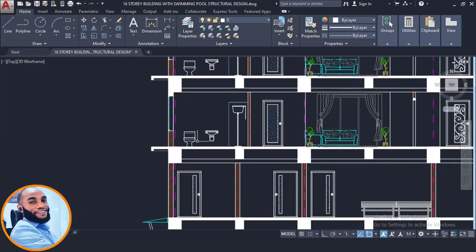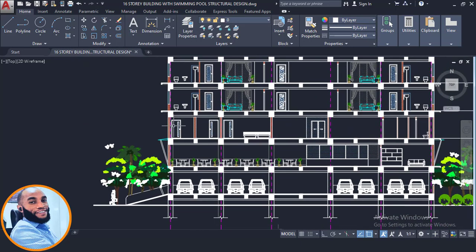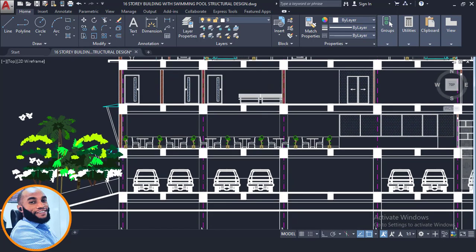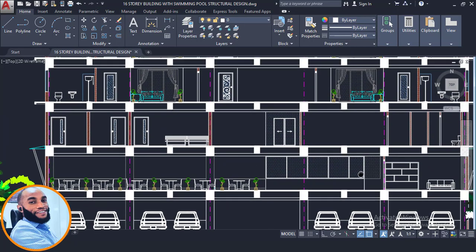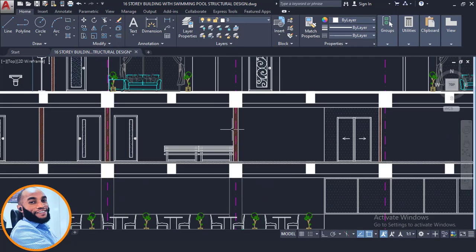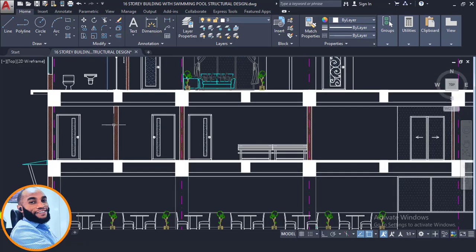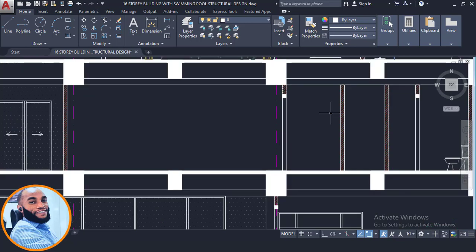That's fine, although there are some loads. Let me see. On the second story right now we have loads. You can see that the wall load is on this other side, but on story 1 here, there is no wall load on this internal place. But on story 2 we have a wall load on this side. This hash here means wall load, on this side and on this beam. Then there is nothing around this place except these ones, which are line loads that can be taken care of by our slab dead load.